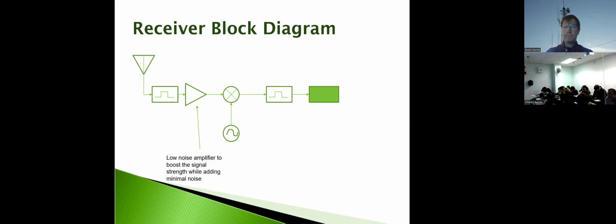And so if you put multiple strong signals into that amplifier, then you will drive that amplifier closer to saturation, into its nonlinear zone. So it will begin to compress, and instead of having a gain of G, it'll have something less than that, because it can't keep producing infinitely greater output power.